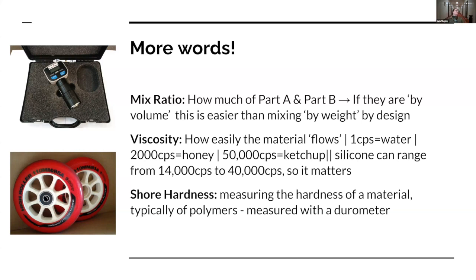It's going to cure way faster. You might not be ready for it. So when you're working, if you've got a lot of something, space it out, spread it out to give yourself extra time. That's a frequent point of crying when you've bought some expensive epoxy and you leave it in your bucket and you turn around and it's kicked, it's hard, it's done. You didn't pour it on the thing you wanted.